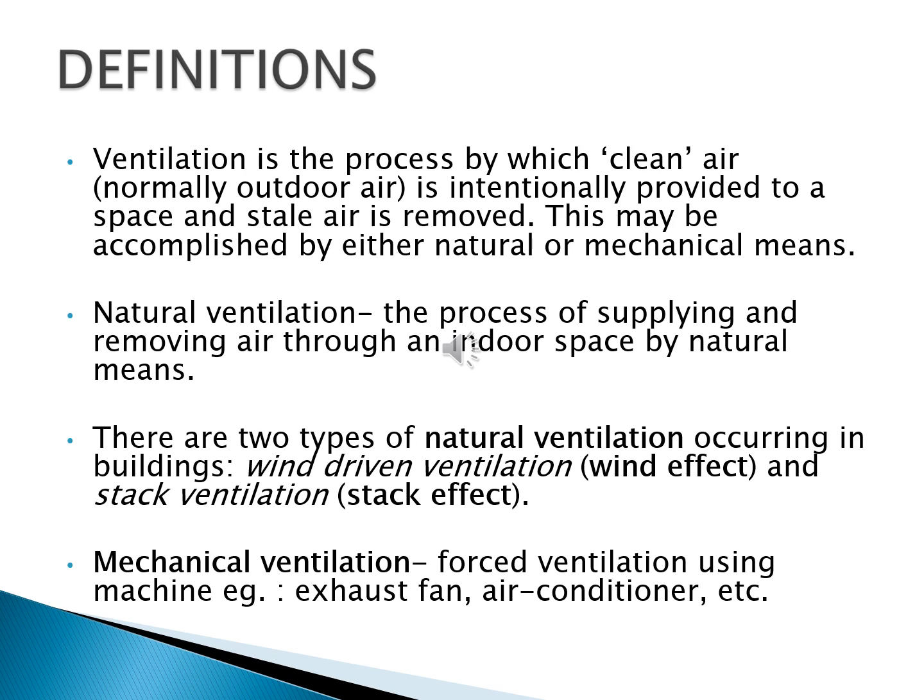There are two types of natural ventilation occurring in buildings: wind-driven ventilation or wind effect, and stack ventilation or stack effect. Mechanical ventilation is forced ventilation using machines, for example, exhaust fan, air conditioner. It is used for applications where natural ventilation is not appropriate.